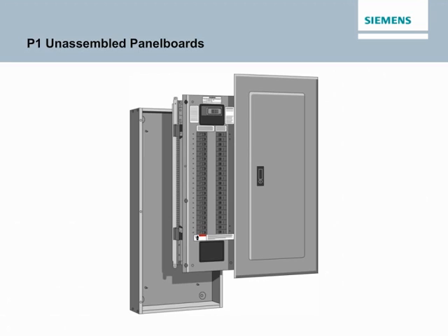The panel has space to add a sub-feed breaker up to 250 amps, feed-through lugs, or a TPS-3 surge protection device kit. Siemens standard trim has hidden hinges and mounting hardware for added safety, and the panel door has a semi-flush lock as standard.